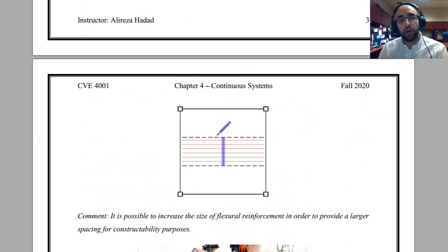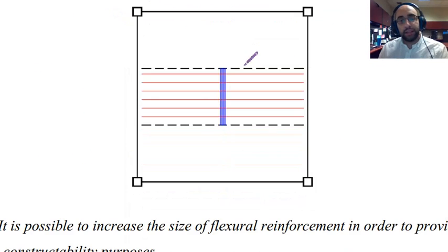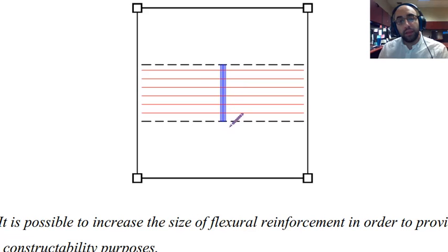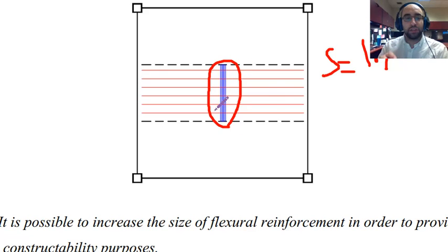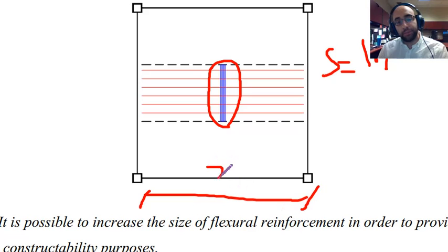If I want to show you all of these reinforcement in the actual problem, these are the flexural reinforcement. We said at every 12 inches we have 5 number 3 bars, and the spacing was 1.7 inches. That's why these are very close. Of course, we are looking at the top, and over here this length that you are looking at is actually 30 feet.